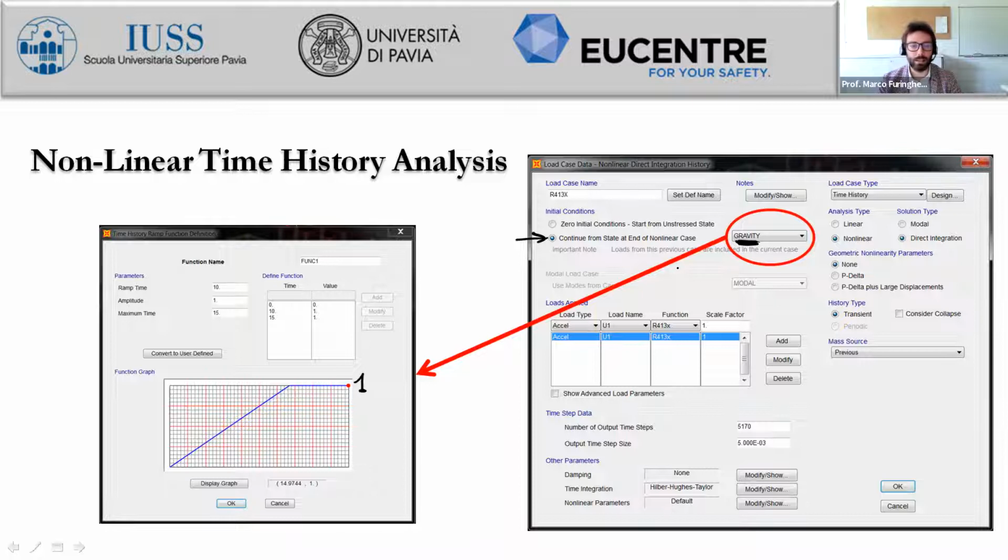Generally, I think that Rayleigh damping could be fair enough, rather than stiffness proportional. Maybe it is much more conservative, but we have also performed some computations with Rayleigh damping by considering from 2 to 5% of damping ratios. And regarding the other question about which periods to consider for the definition of the Rayleigh damping, we know the drawing of the damping ratio with respect to the angular frequency. It is something like this.